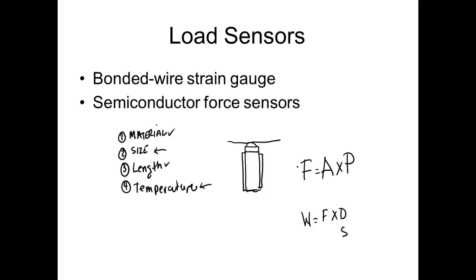Now, what did it do? What would happen if I was measuring the resistance of this thing? What would happen to the resistance of it when the truck came on? Well, the resistance would go down because not only did it get shorter, it got what? It got fatter, right? You understand that? Well, this is not what we measured. What we would do is slap something on the side of this that would actually have the ability to measure how much it expanded.